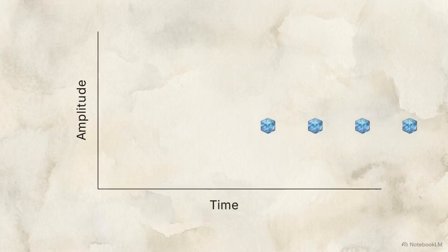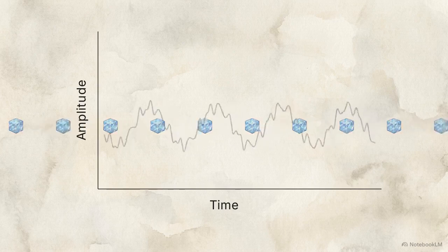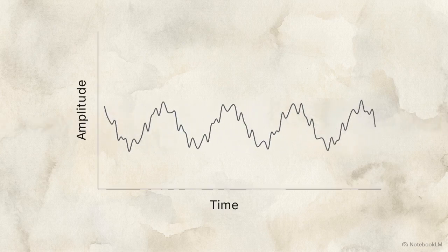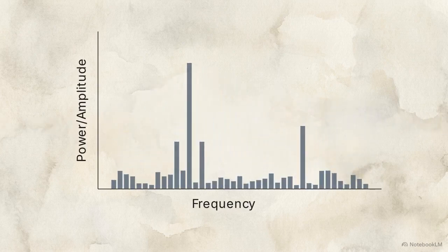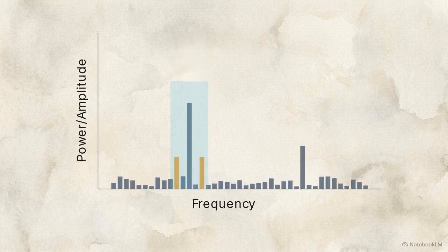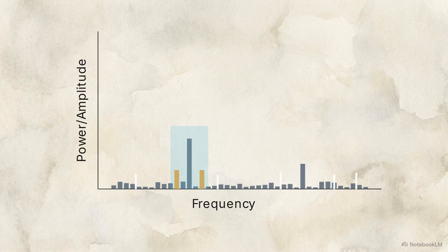This diagram shows the digital signal processing layer. A raw time domain waveform transforms into a frequency spectrum using fast Fourier transforms. Through motor current signature analysis, the system isolates frequency bands to track broken rotor bars. We also layer additive spectral kurtosis onto the spectrum, isolating sharp mechanical shocks from the motor's standard background noise.